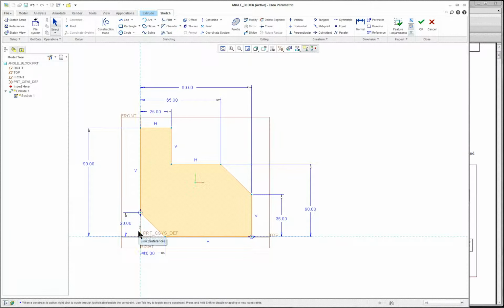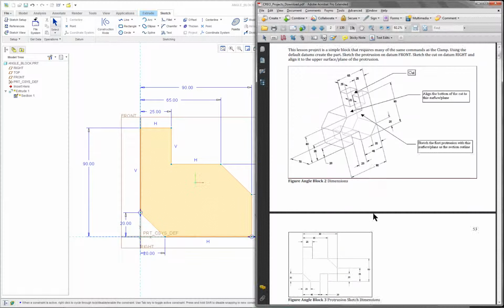One of the things you should notice, we did put this big chamfer on here because it's a large angle cut, so I think it should be included. This is all pretty much adding material. You'll notice I did not put the little cutout in that belongs on the part. And there's a reason for that. That should be a separate feature.